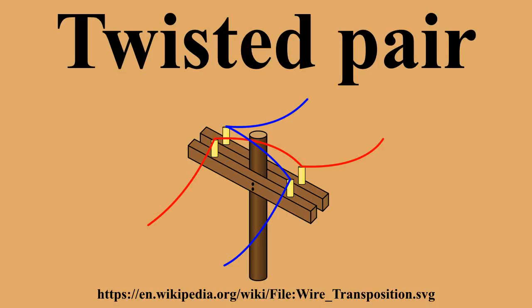Explanation: in balanced pair operation, the two wires carry equal and opposite signals, and the destination detects the difference between the two. This is known as differential mode transmission. Noise sources introduce signals into the wires by coupling of electromagnetic fields and tend to couple to both wires equally. The noise thus produces a common mode signal which is cancelled at the receiver when the difference signal is taken.